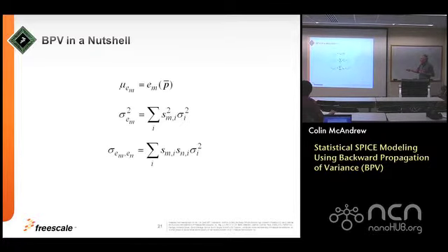And this is, I make a sequence of measurements, and that gives me a sequence of measured variances in threshold voltage for a wide long, threshold voltage for a wide short transistor, peak GM for a long transistor, ID-sat for a short transistor, and I'll explain why we choose those. And then I've got sensitivity squared, which I can calculate, and I'll tell you that in a minute. And then I've got a sequence of unknowns, which is the variations in the parameters. So that gives me a set of linear equations that I can just directly solve to give the variations.